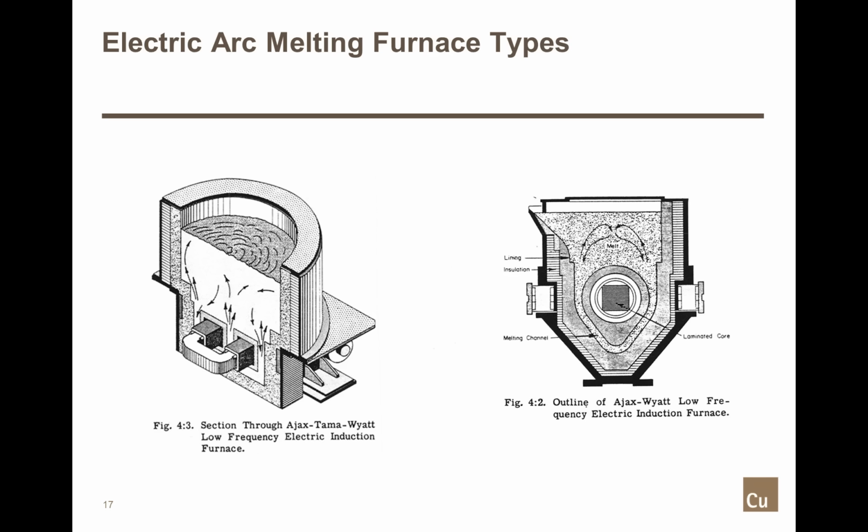You can make copper nickel in these. You can make a bronze, a variety of other materials. And in that way, you're only making a relatively small amount, whereas in a reverberatory furnace, which is much larger than these, you would be making 120,000 pounds at a time. So the volume is different.